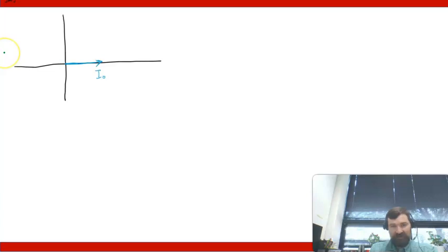That means that at that same time, the voltage drop across the resistor, VR, would be represented by this second arrow here. And our voltage drops for the inductor and for the capacitor are going to be represented by this pair of arrows, VL naught, and for the capacitor, VC naught. Note that VC naught plus VL naught would be this arrow right here.